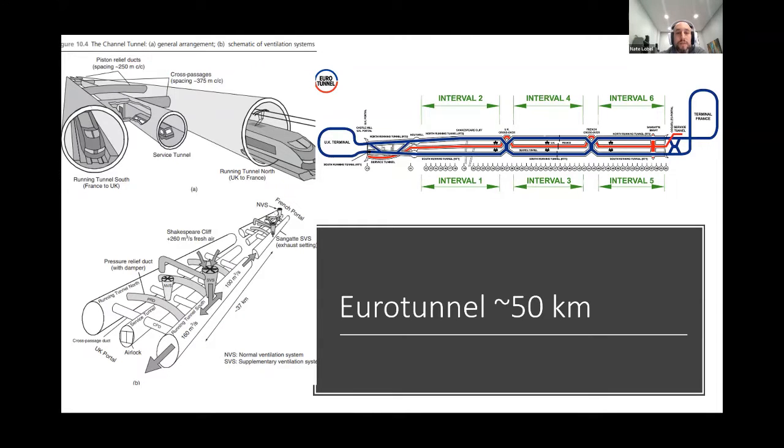The original design of the Eurotunnel didn't have any fixed fire suppression. After a fire, they installed fire suppression at 4 specific points, with the idea from some analysis that a train, even disabled by fire, should have enough momentum to make it to one of those points to make fighting the fire easier. It's quite an interesting system, and a good showcase of how to design critical systems with some redundancy so that the entire environment could continue to operate.